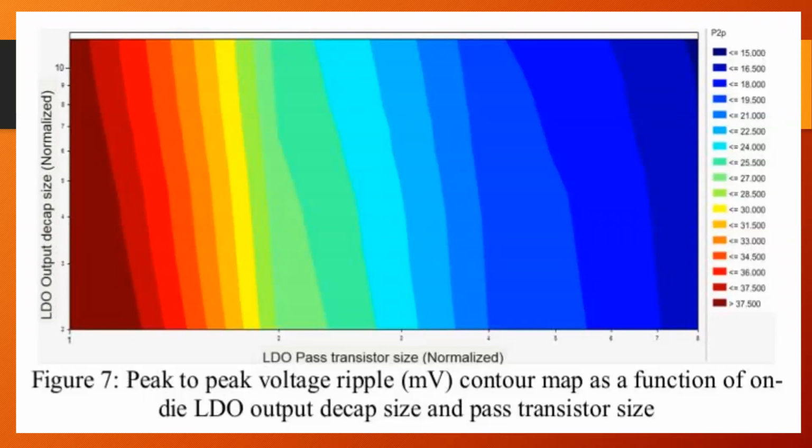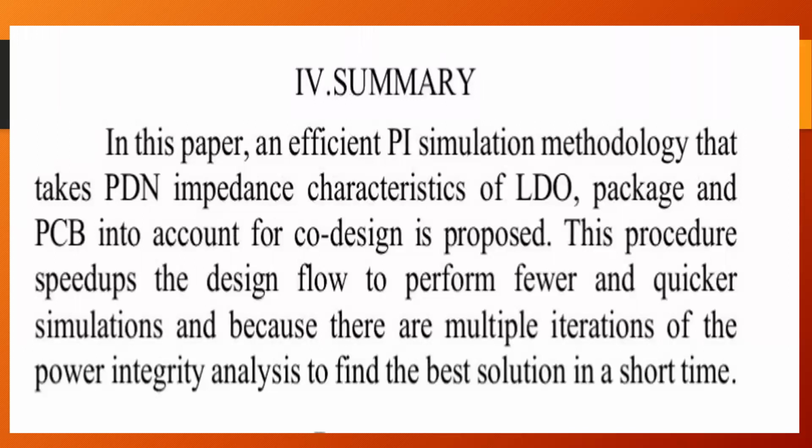In this paper, an effective PI simulation methodology that takes speed and impedance characteristics of LDO, package and PCB into account for co-design is proposed. This speeds up the design flow to perform fewer and quicker simulations, because there are multiple iterations of the power integrity analysis to find the best solution in a short time.